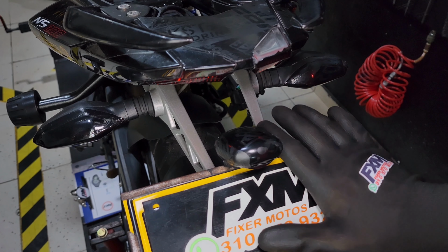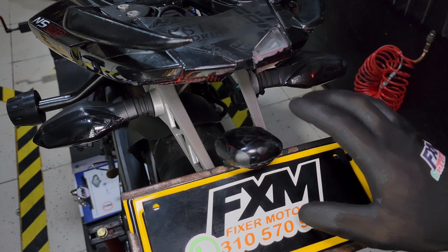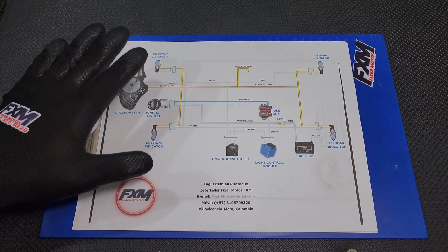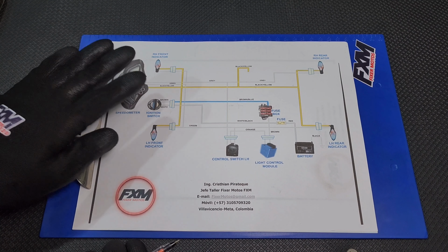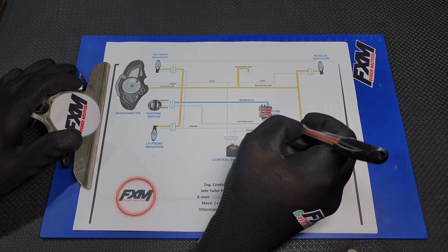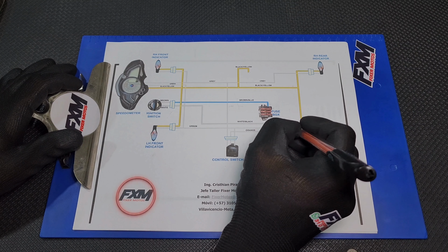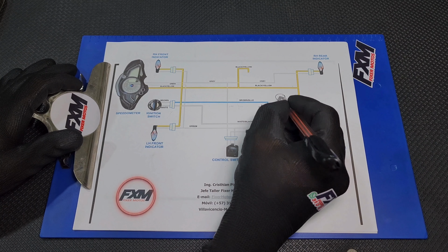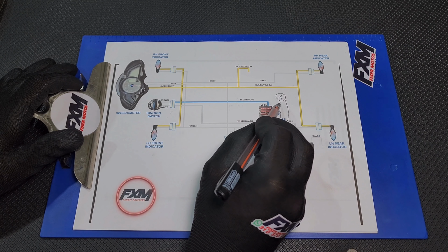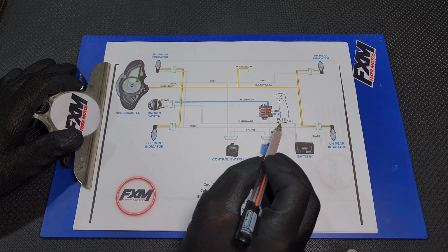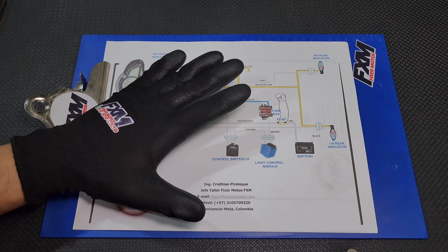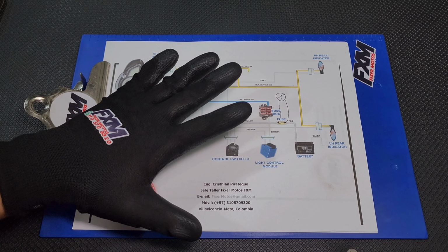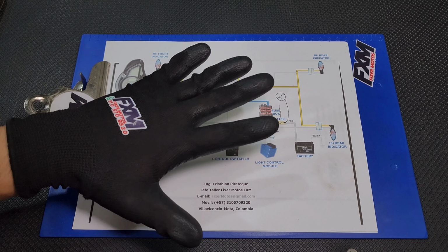I need to give you context on issues of current consumption. For that, we are going to do some amperage tests, and these amperage tests are done to determine the consumption of each element. To do it, what we are going to do is break this circuit. That is, we are going to remove this fuse, we are going to connect the two leads of the multimeter, and we are going to measure the number of amps that pass through this circuit. In the basic electricity module, I am going to explain these in a little more detail. For now, we are going to do this reading on the motorcycle.